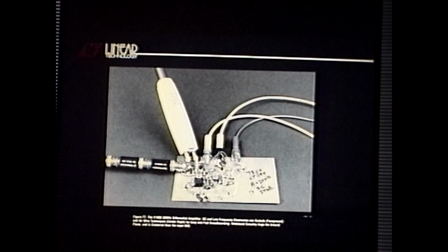I could wire the DC stuff back in here if I wanted to, but in my case it just takes too much time. There's no point. The other thing you'll notice I'm doing is this is a gain of 1,000 amplifier, so I've got to generate an input pulse of millivolts to drive this thing. I could just take lots of attenuation out of the pulse generator, which is what I'm doing here with a stacked attenuator set, and believe that the pulse of millivolts here must be as clean as the pulse of volts here from the pulse generator, if I believe that my attenuators are that good.